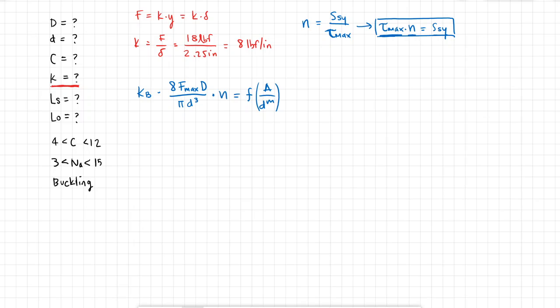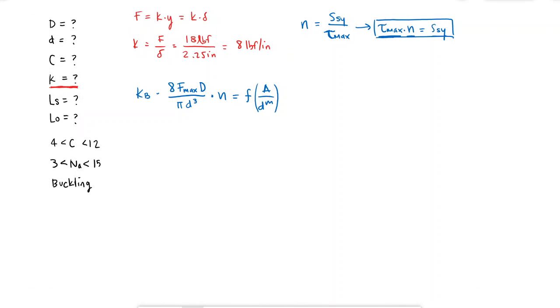And this fraction f of the ultimate strength is also given by the type of material I'm using. So from the tables that we saw in class, I know that the fraction of the ultimate strength for cold drawn steels is 0.45. This is from the table that tells me before and after the preset, and in this case there's no preset because we want to avoid yield. That's exactly what the problem is telling me.